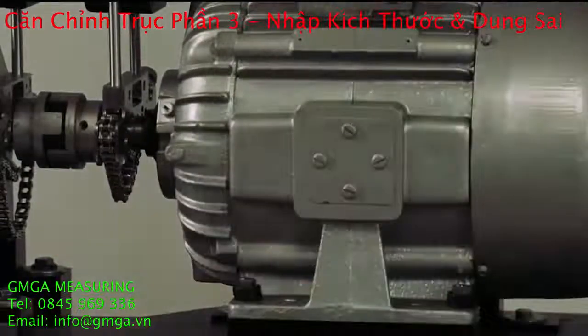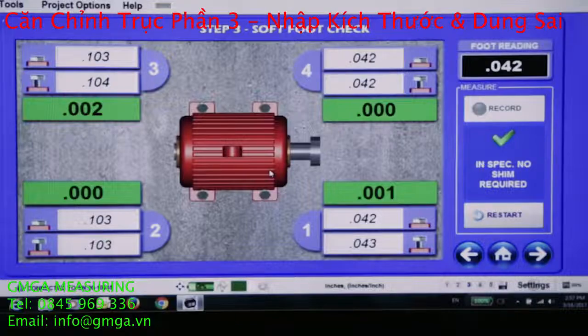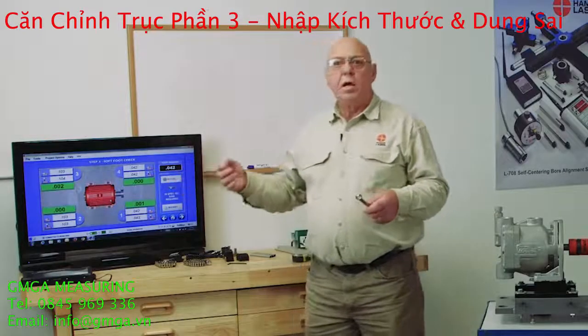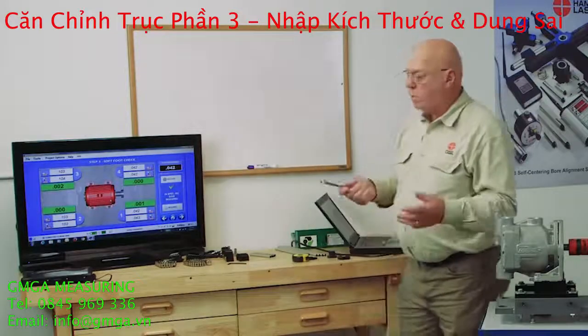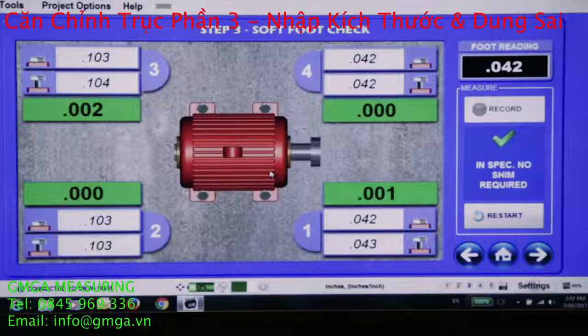Now this particular unit doesn't have any soft foot. If I had a soft foot, this would tell me, like here is 2/1000ths, that's acceptable, 2/1000ths of soft foot is acceptable. If it was greater than that, it would turn red and it would tell me to either take some shim out or add some shim to that foot. I would do that and correct it. But now it's good, so we'll just go on to the next step.